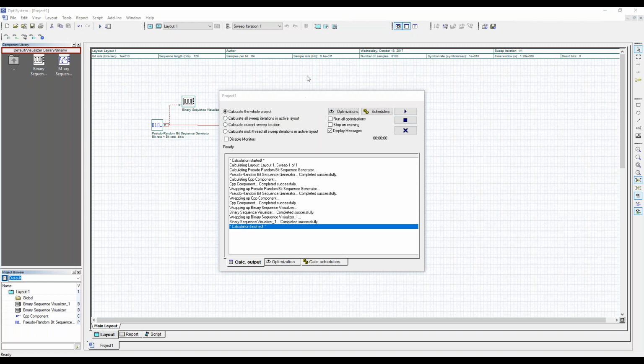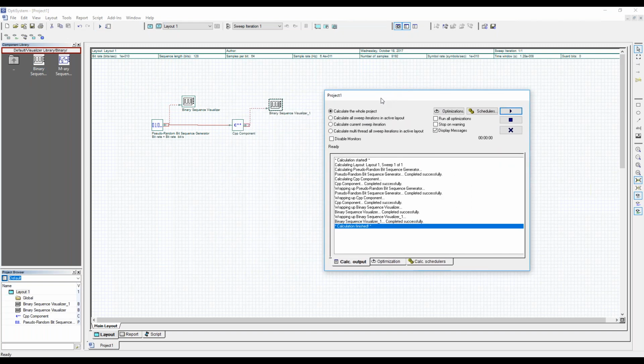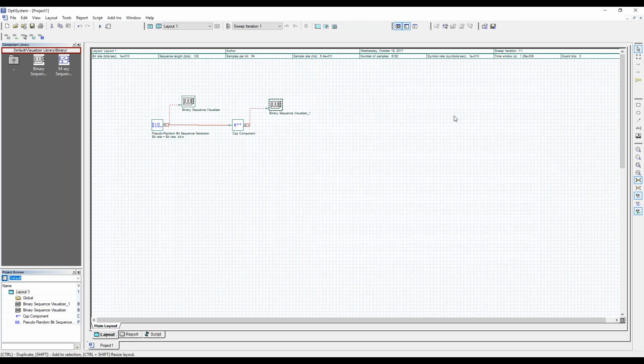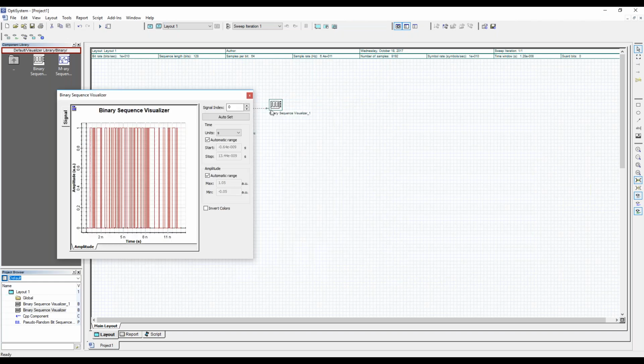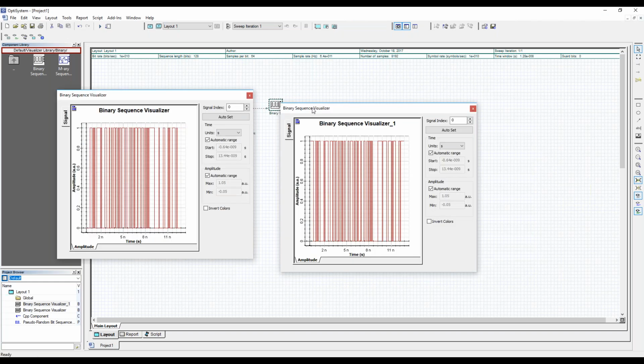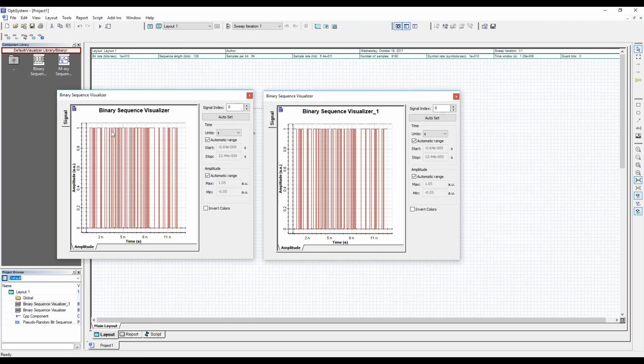It's native speed, so there's no intermediate step where you have to wait for OptiSystem to open up Matlab. We should see here that we have the modulo 2, or the opposite, of that input binary sequence. We've got a low value in the input, and the output has a high value. And that's how you would use the C++ component to get your first interface going.